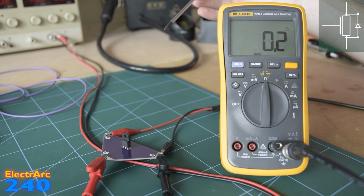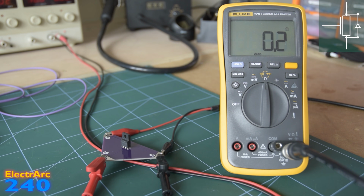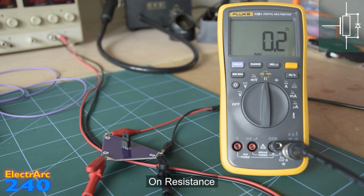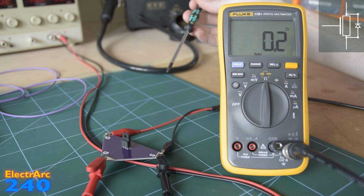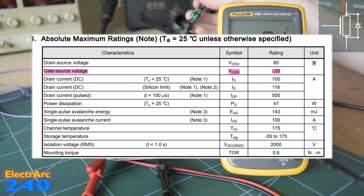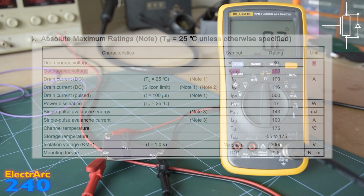Now, this is partly to do with the fact that we're below the minimum resistance that this multimeter can read. But it's also because MOSFETs have something called on resistance, which is a resistance that's always present no matter how hard you drive the gate. And there is a limit to the gate source voltage that you can see here in the datasheet, and it's very important that we don't exceed that, or really that we don't get close to it at all, because that will instantly destroy the MOSFET.